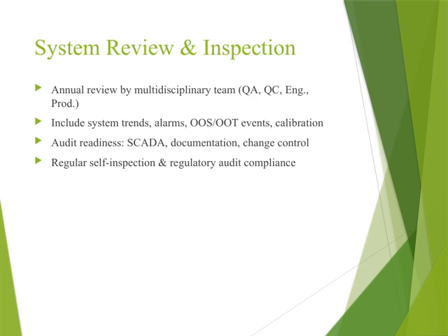During this review, we focus on tracking system trends, which help us identify patterns or potential issues early on. We also review alarms and any out-of-specification or out-of-trend events, or OOS/OOT events, to understand their root causes and prevent recurrence. Calibration is also checked to ensure instruments are accurate and reliable.